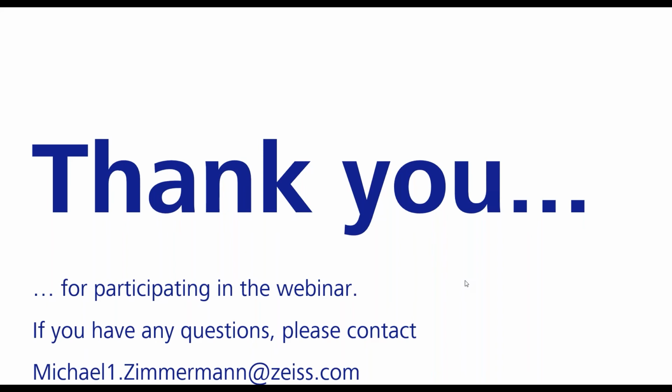This means that you do not have to spray the component with a matting spray before the measurement, as is the case with a triangulation sensor. This would naturally change the surface and then the dimensions of the part. With the dot scan, it is possible to avoid that, and it's even possible to go so far that you can measure the thickness of layers depending on the material. Hope that answered your question here.